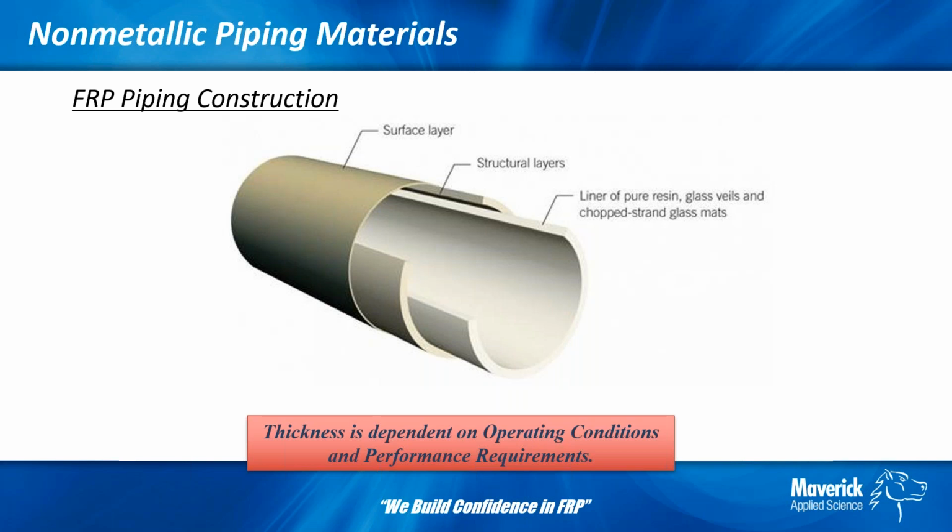So this is where the right pipe supports are important. And largely, depending on the pressure rating, that's where we get into more custom applications, where say drain piping might be only 25 psi, where full scale pressure piping might be 150 psi, and there'll be completely different ODs, so you have to match the supports for that.